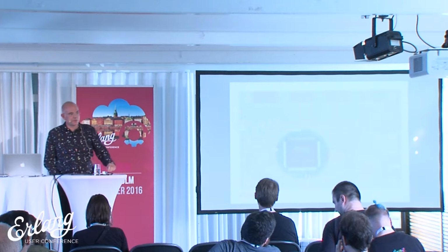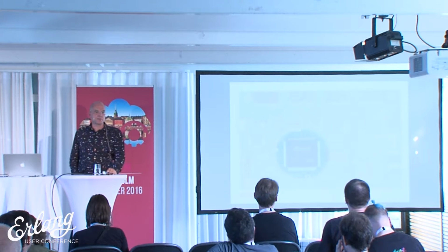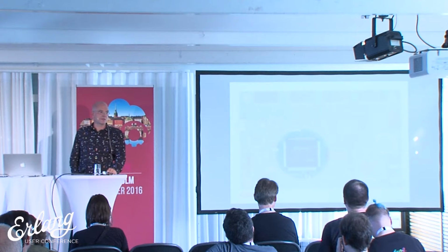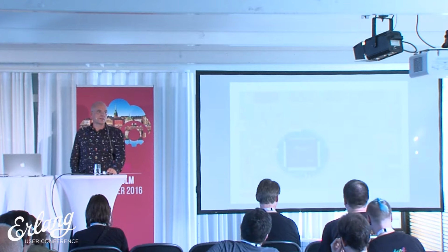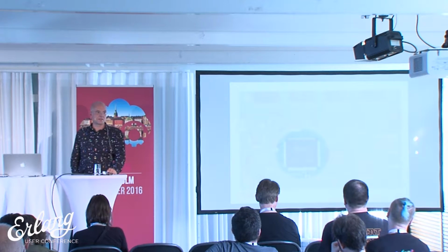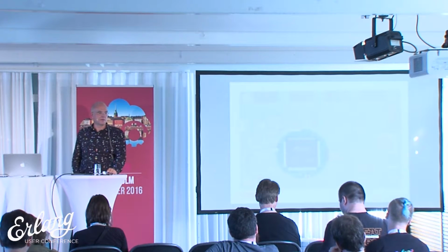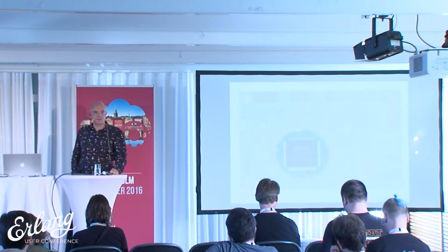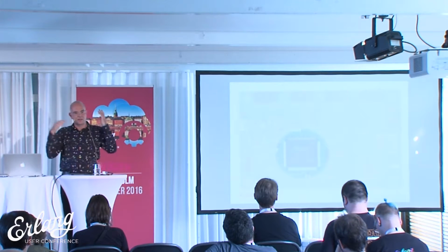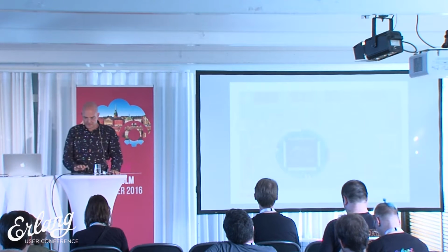So that's the CPU. It's an Atmel CPU, but it's not the Arduino class CPU from Atmel, it's an ARM core. It's a Cortex-M7. That's the largest mobile, low-power ARM design that you can get. So it has 32 bits and an FPU and everything you need.